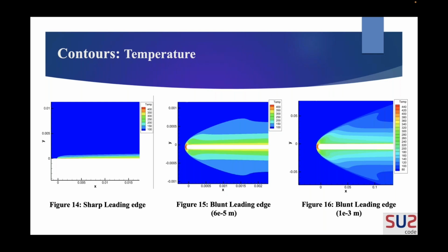It is that point where the boundary layer swallows the entropy layer, and then the transition occurs. The distance between the nose radius and that entropy swallowing point is said to be the entropy swallowing length. As we increase the bluntness, we also observe that the entropy swallowing length increases. And since the entropy swallowing length increases, the point at which the boundary layer takes in the entropy layer also moves downstream. Thus, it delays the transition.